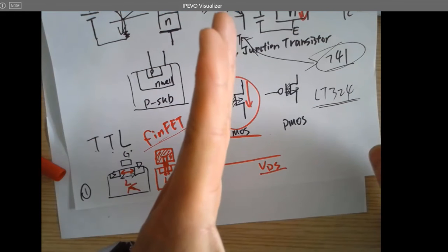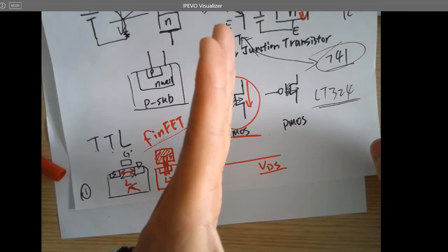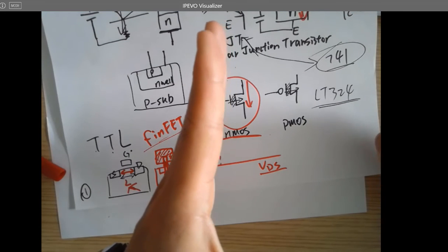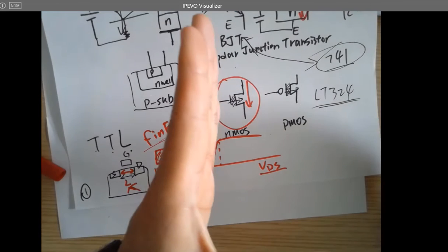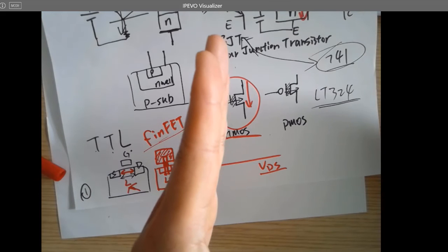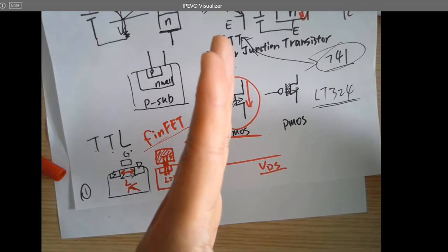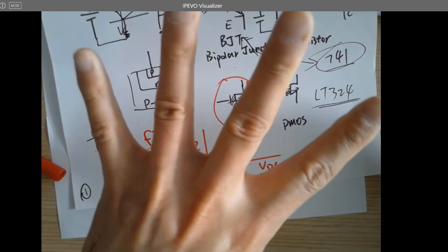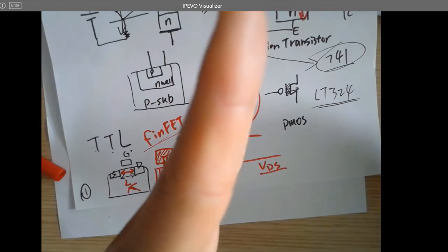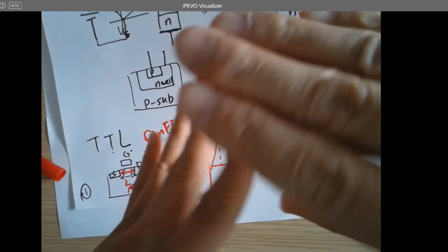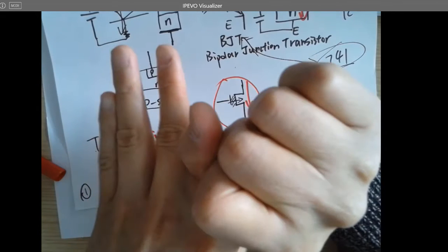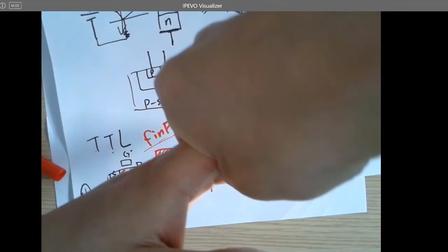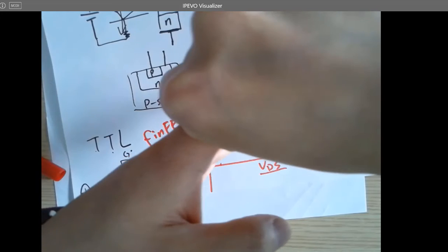You don't want a fin. What's next? You can imagine. For 3 nanometer, Samsung developed it, and it's going to be available in 2 years. They're not using fins anymore. They start using wires, so the channels are wires. This is the fin, and this is the wires. They have wires like this and have the gate not just wrap it up like this, it's going to totally wrap around it, in some of the extreme cases for 3 nanometer technology.